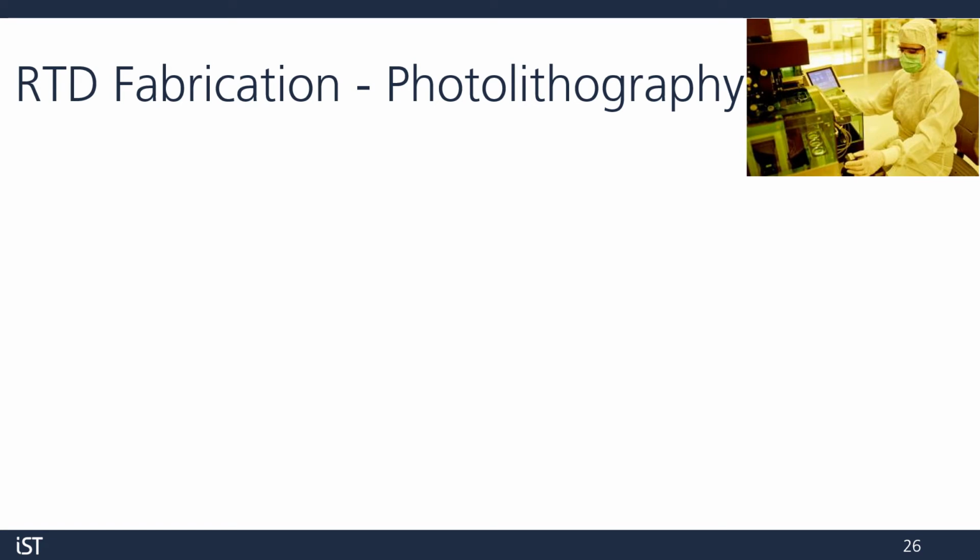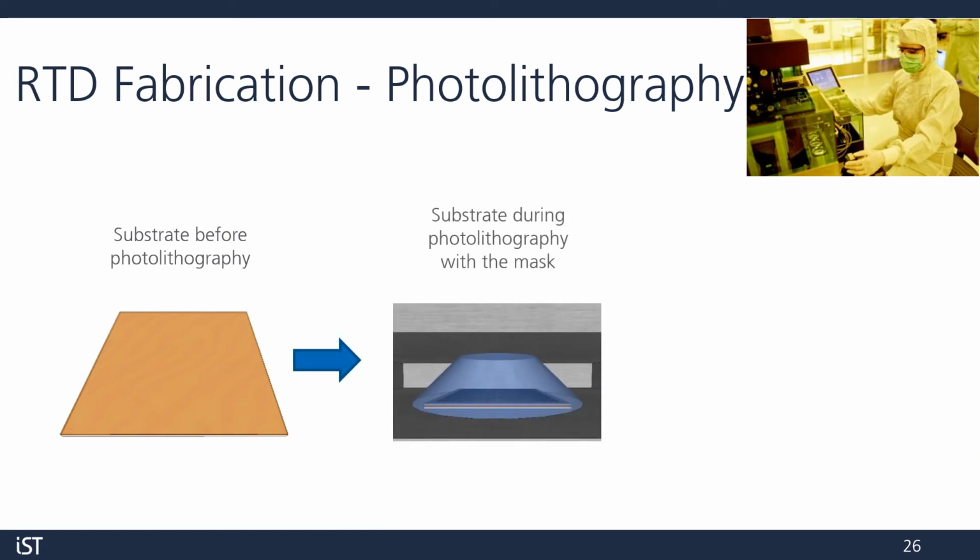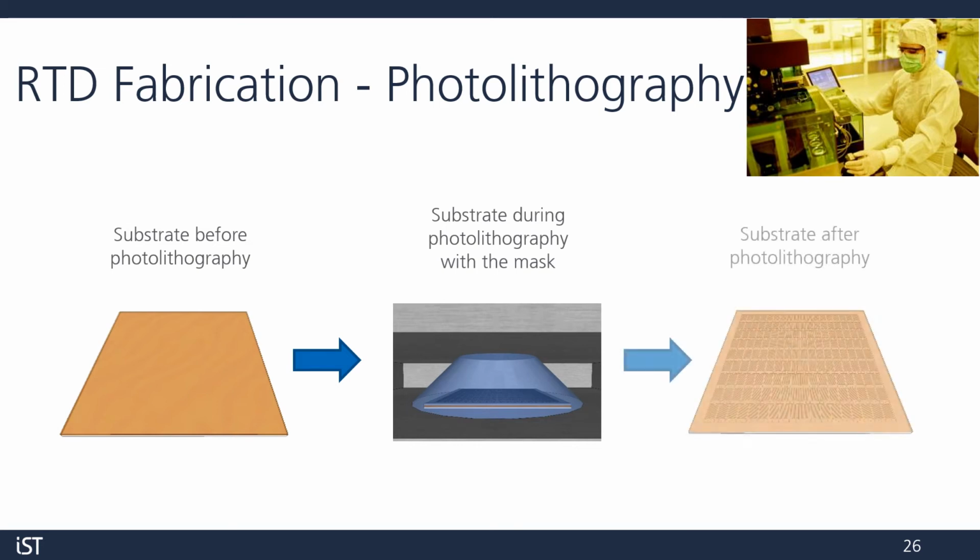Now that our photoresist is applied, we can perform a process called photolithography. We take a piece of glass with a metal drawing of our platinum meander and contact pads. This is called the photomask. Then, we align it closely with the substrate and a brief burst of light is applied. Only the parts left exposed by the mask are exposed to the light. These exposed areas are washed away during a subsequent chemical development process.